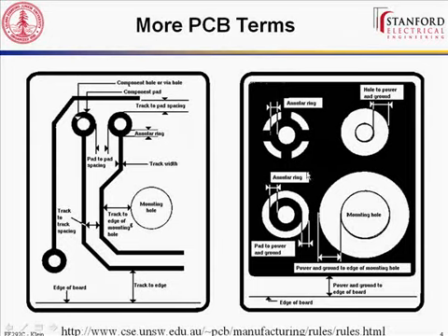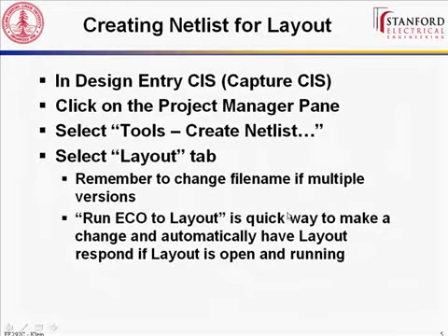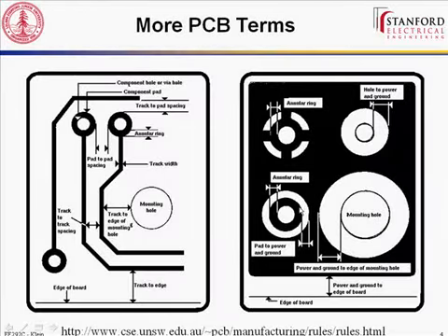So when you have this connection here, the white part in the center is the actual drill hole. So anything that you put through this hole right here will connect to this plane layer, because black is copper. Anything you put through this hole, because the white is the drill hole and the black is the actual ring, you can solder, but it's not connected to this layer. Because remember that this view is just one layer of many on your board. So just because it's not connected on this layer doesn't mean it's a worthless via or hole to have. Does that kind of answer the question?